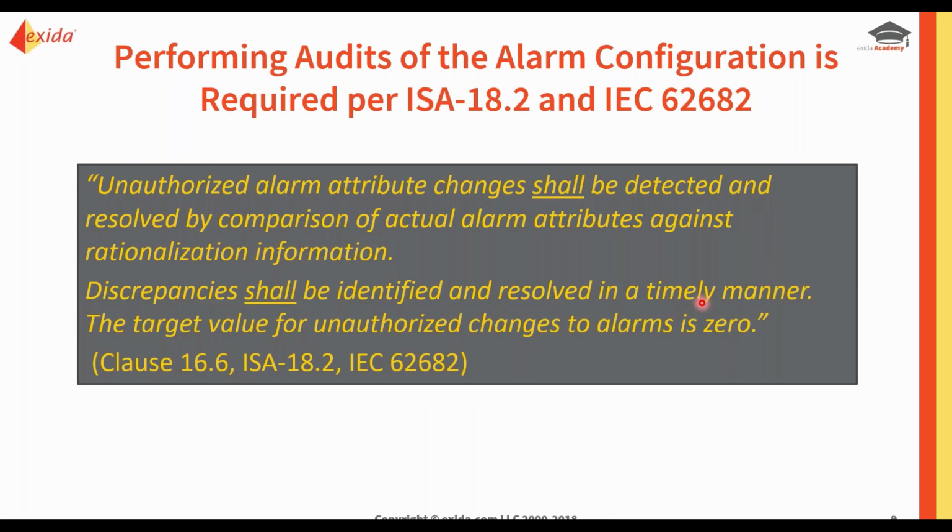So let's look at what the standards require when it comes to auditing and enforcement. Both standards say the same thing. They say unauthorized alarm attribute changes, and when I say alarm attribute, I mean something like the alarm limit or the alarm priority, shall be detected and resolved by comparison of actual alarm attributes against rationalization information.